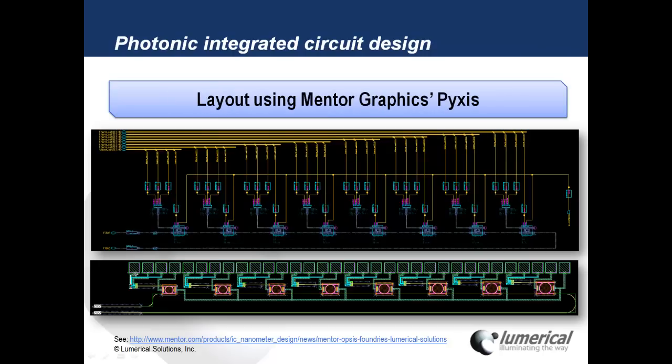Now, just to give you a quick idea of how this can work, the idea is that you can lay out extremely complex photonic circuits using a tool like Mentor Graphics Pyxis. And this is an example of a portion of an 8-channel WDM transceiver. Once you've laid this out with Mentor Graphics Pyxis, you get all of the excellent features that come with an electronic EDA design flow. So you can do design rule checking, layout versus schematic, and that type of thing.